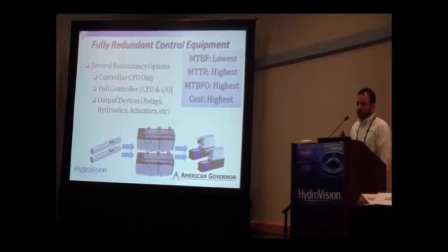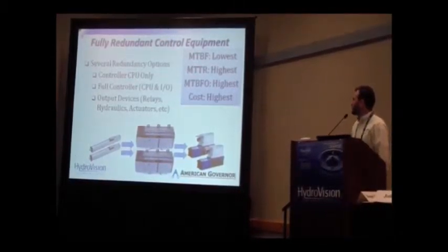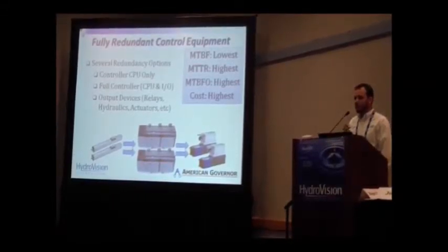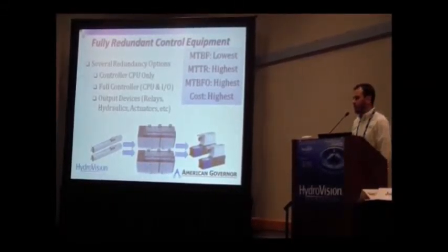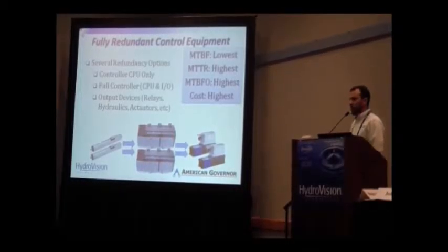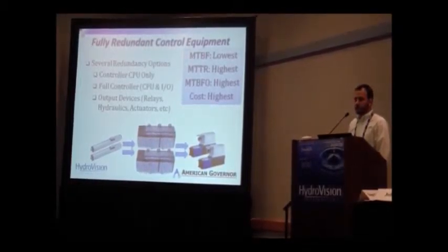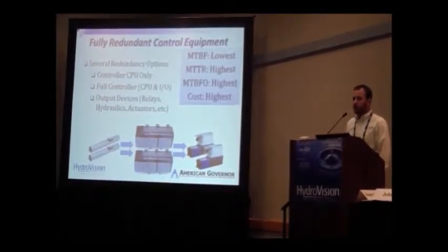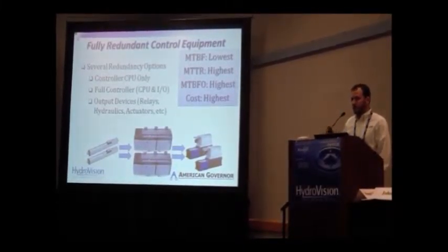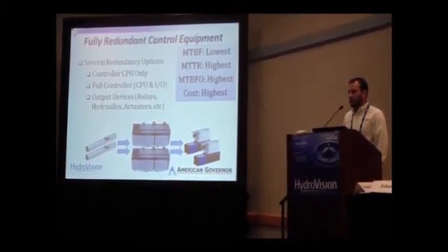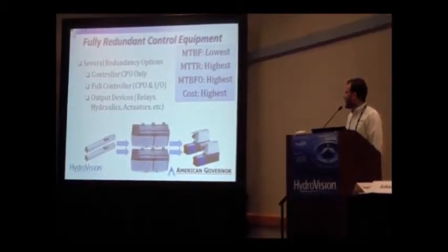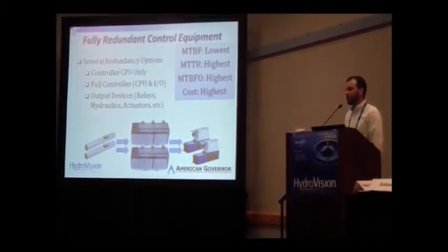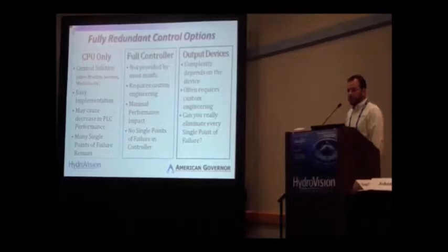These controllers, through the spectrum from the simplest to most advanced, will lower your mean time between failures. Again, same trend. More equipment, the higher probability that you're going to have a failure. It will raise your mean time to repair because your system's getting more complex. But it will also significantly raise your mean time between forced outages because you're striving towards that kind of ambiguous goal of no single point of failure. And your cost will be the highest, not just in equipment cost, but design cost, implementation cost, and maintenance cost.